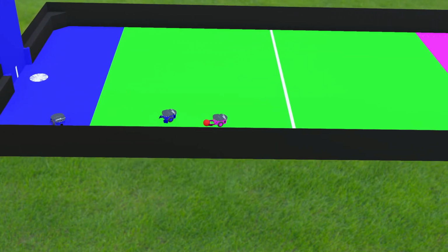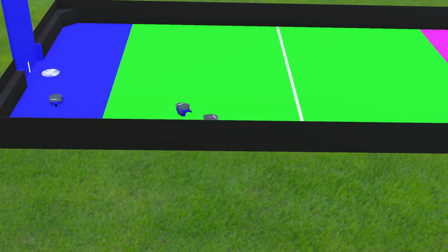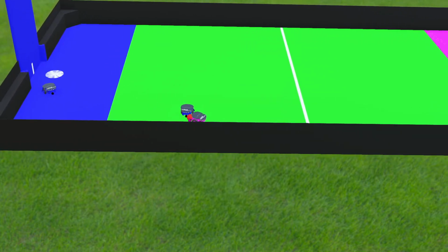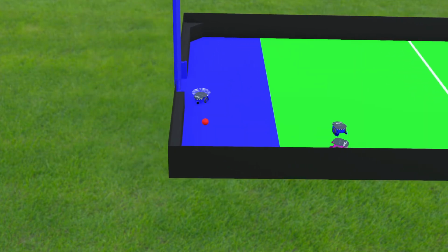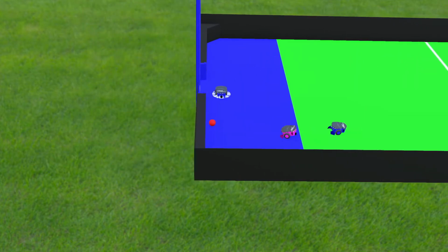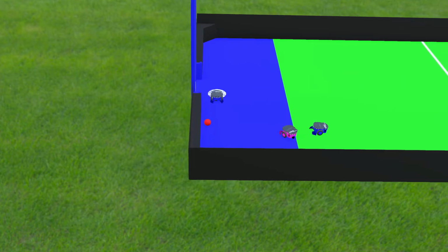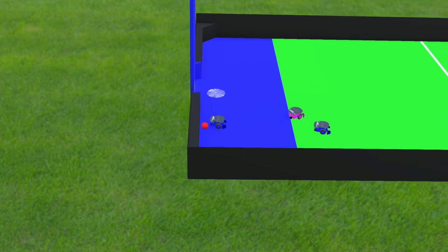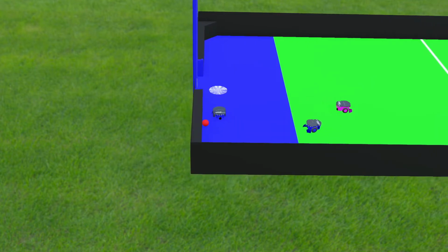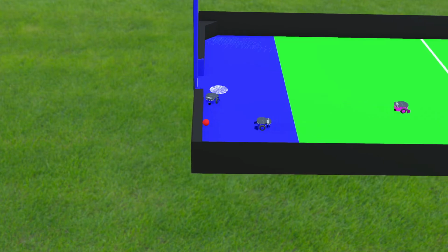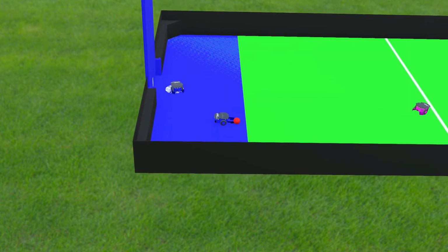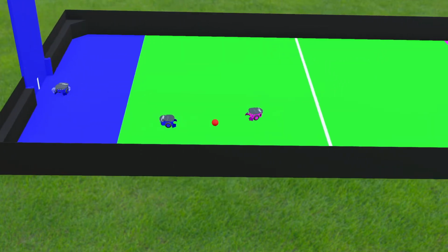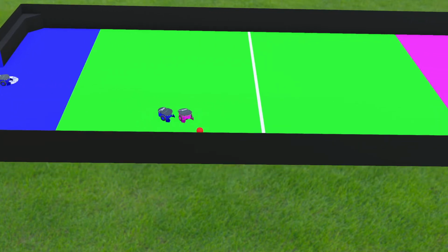And then once the robot has decelerated, it triggers the next state back to the follow the ball state. There are 2 other states which are independent, which are called by some of the other edge case scenarios which are outside the state machine. One of them I mentioned earlier was the retreat state, when it goes on the enemy's goal area. The other is when the robot is detected that it's stuck.